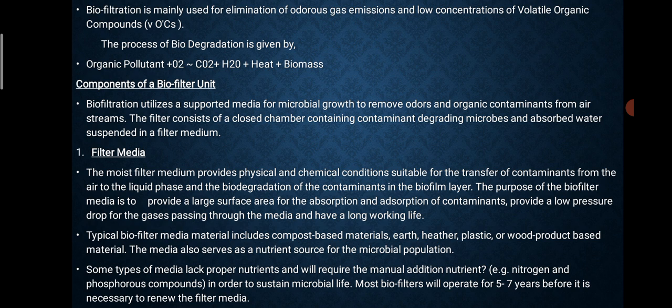The purpose of the biofilter media is to provide a large surface area for the absorption and adsorption of contaminants, which provide a low pressure drop for the gas passing through the media and have a long working life.